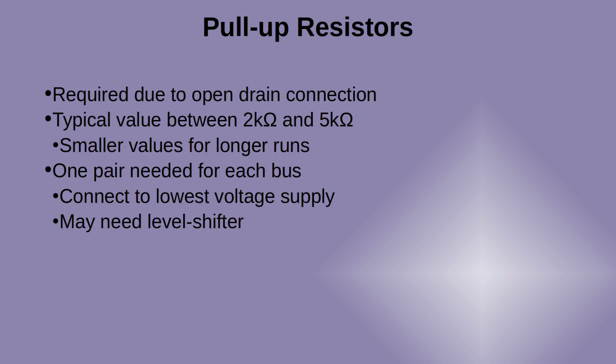You don't need to add additional resistors when you add more devices, as long as there is one pair of resistors. An exception is if you do use a level shifter, when you need to ensure there's a pull-up for both sides of the level shifter. The example I used in my earlier video includes a 10 kiloohm pull-up resistor anyway, but you may want to add a smaller resistor.